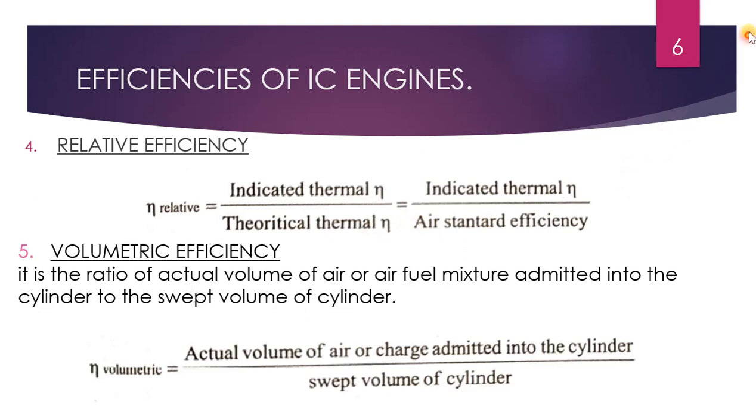Another efficiency is volumetric efficiency. It is the ratio of actual volume of air or air fuel mixture admitted to the cylinder to the swept volume. You know what swept volume is. Volumetric efficiency is equal to the actual volume of air or charge admitted into the cylinder divided by swept volume. You need to study the definition of this efficiency only.